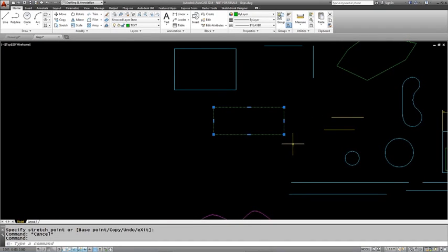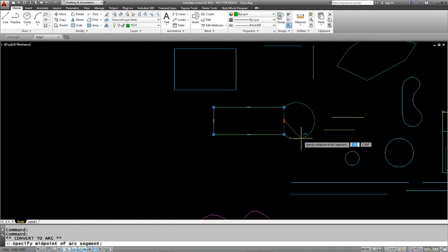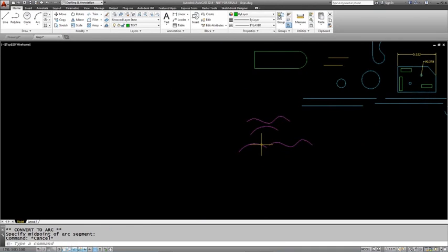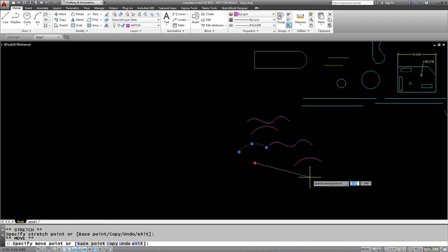Well, it's a polyline. And a polyline, again, if I hover, gives me multi-function grip capabilities. And different locations give different multifunction grip capabilities as I select those. So you need to walk through those. What do we have down here? This looks like an arc. Yes, it's an arc. And again, you can see the different multifunction capabilities depending where I hover over any of the grips. Now in this case, when I select the center of that, that goes back to my grip modes.